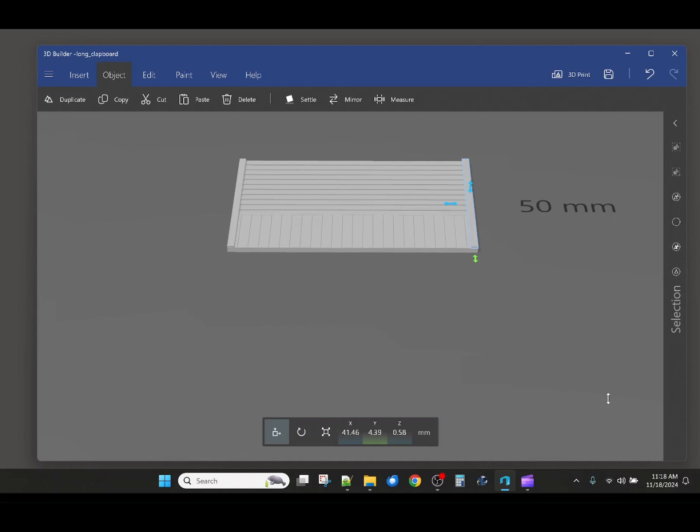Next, we need to make 45-degree bevels in the wall corner edges so we can glue individual wall parts together after printing. To do this, we'll use the Subtract tool in the Edit category of the menu. This tool will take one part and subtract the material from a part it overlaps. To do this, we'll use the cornerbevel.stl file. Insert add it like the other files.